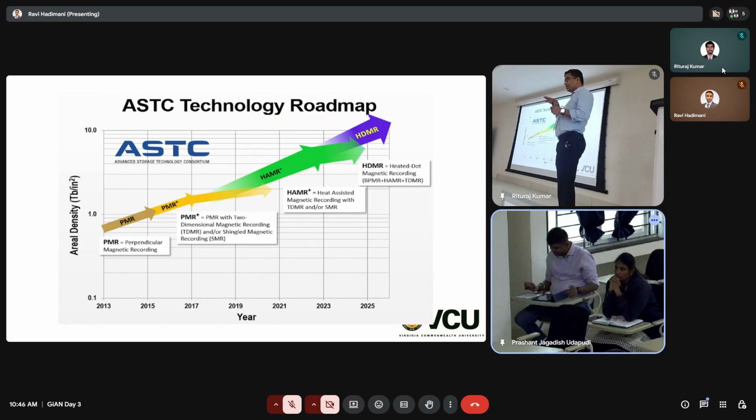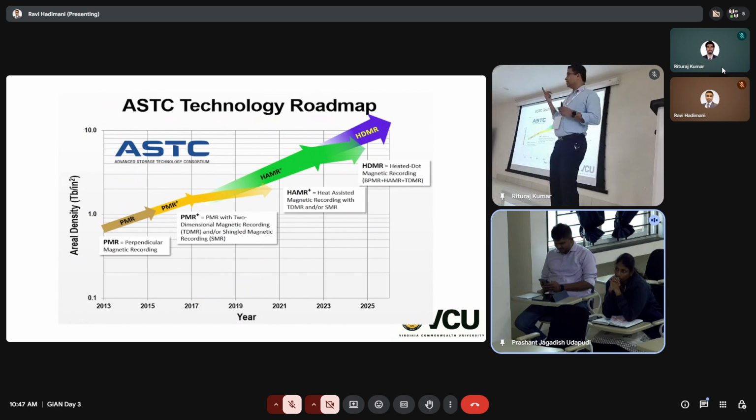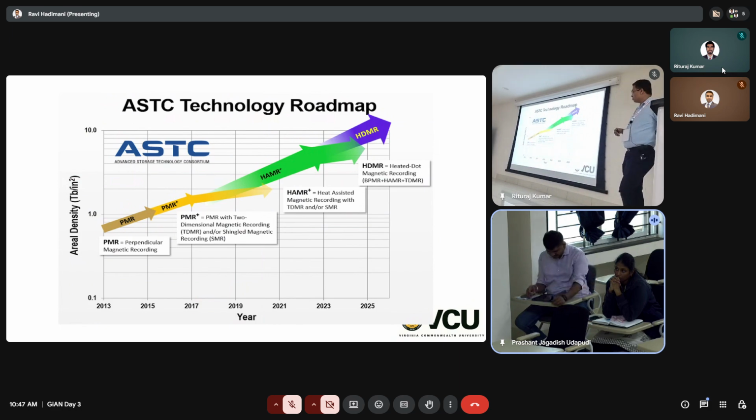And that is more sensitive than the hard disk platter when you magnetize and demagnetize. You can have a lot of cycles of magnetization and demagnetization, whereas with charge movement, after a certain number of cycles, they degrade. So that is another. One is the reliability, and the other one is the duration or the lifespan, the number of cycles you can write. So that's another major difference. Okay, any questions so far?